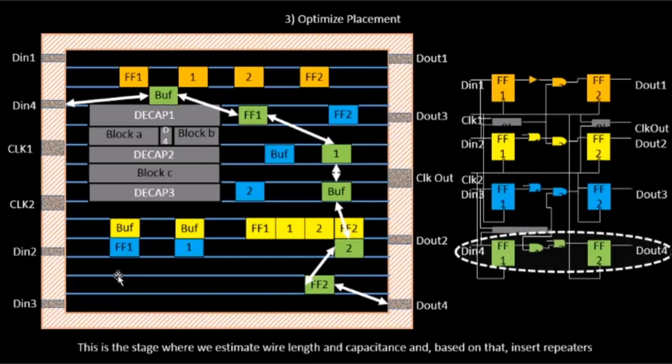Based on the numbers that we get out of the setup timing analysis, we will come to know whether the placement that we have done is reasonable. Based on the frequency, or the specifications that have been given to us, and we'll also note down some specifications, we have to check whether this placement condition is meeting those specifications. If not, then we have to see what we can do, because if it doesn't meet at this stage, it's bound to get bad when we go to further stages of placement and route, or basically the route stage.